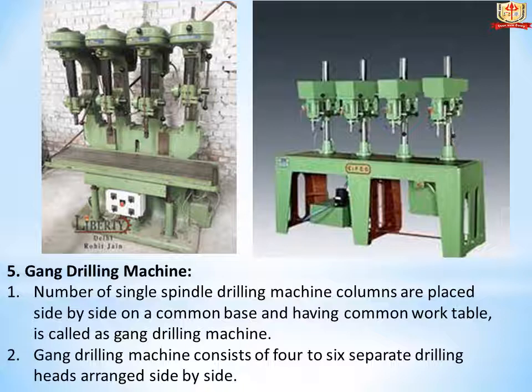Speed and feed of spindle can be controlled independently. Each spindle may be set up properly with different tools for different operations. A series of operations may be performed on work by simply shifting the work from one position to other on work table.